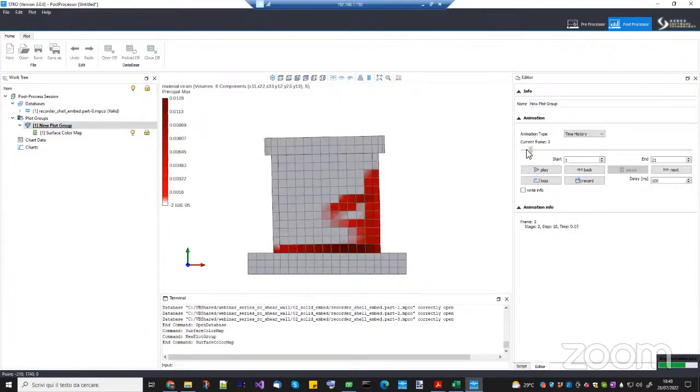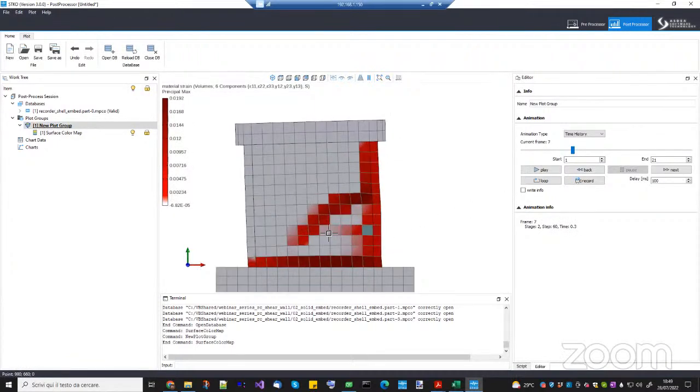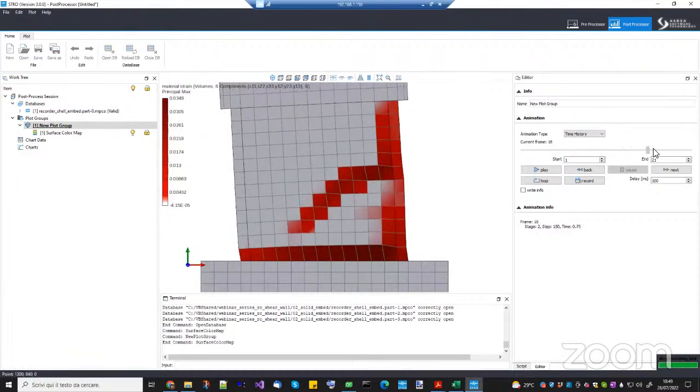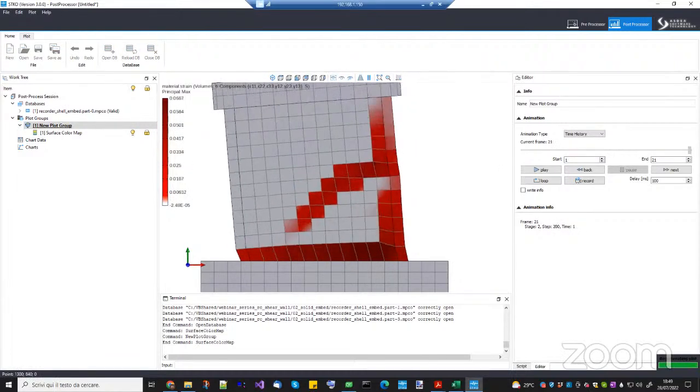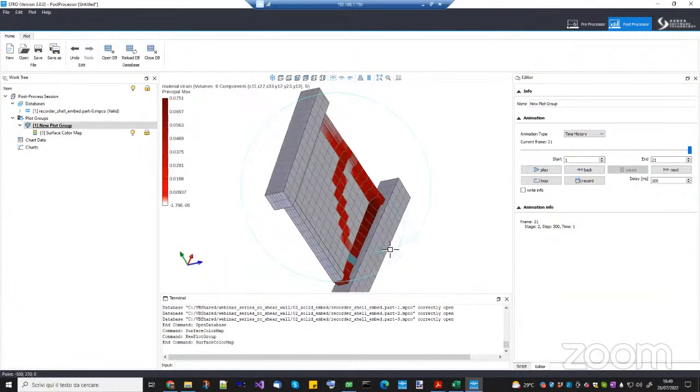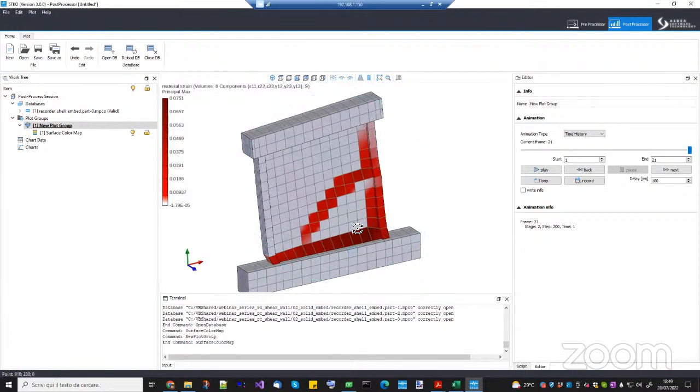Basically, it starts with the initial fracture here at the bottom, then some other flexural cracks, and then you have a change from bending crack to a diagonal crack. If you want to obtain better results, you can go up to here where you have the joining of the diagonal crack to the bottom, and you have the crushing here at the side.